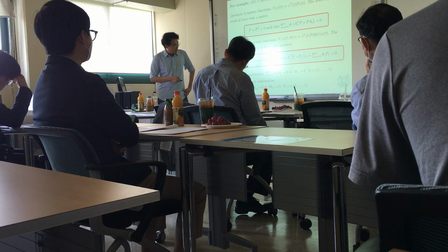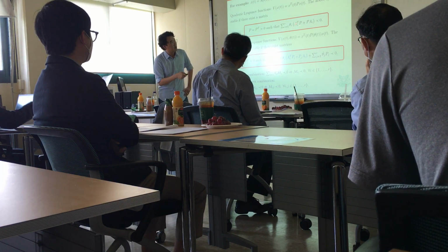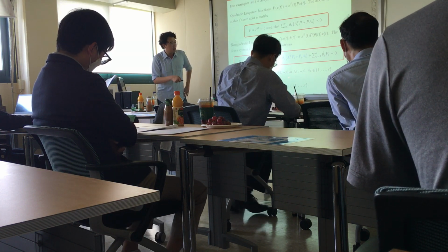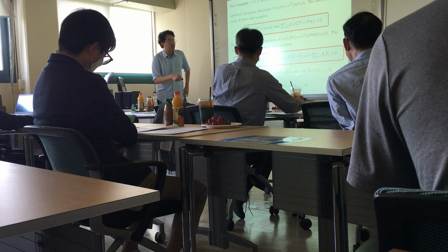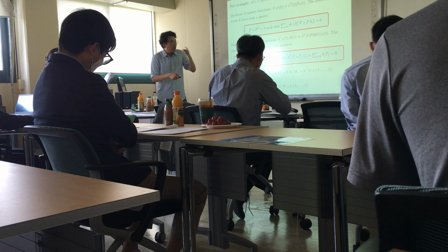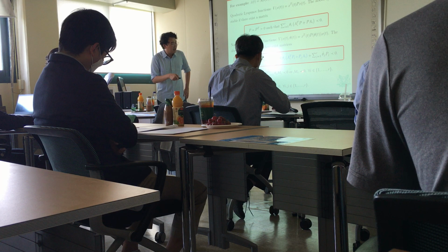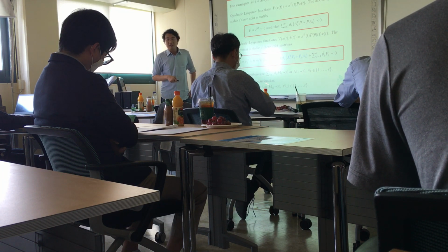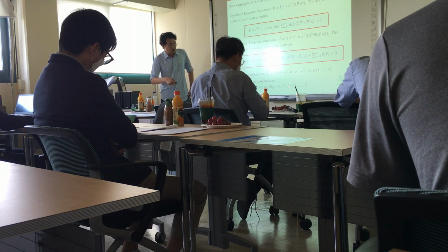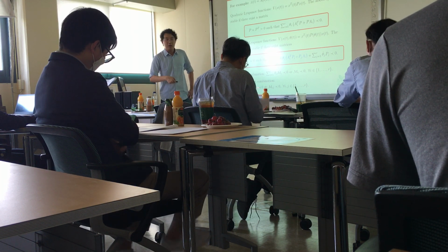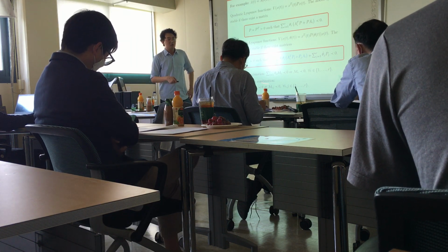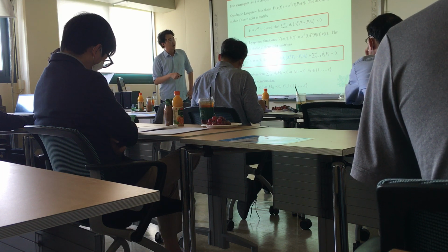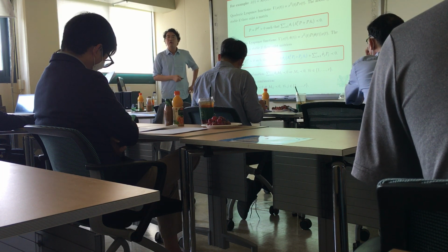Now here is the convex combination, but the convex combination is equivalent to the X matrix being smaller than 0, that is, X matrix is negative definite. In the double convex combination, this equivalence is not true. From the right we can obtain the left, but from the left we cannot obtain the right. That is the reason why we had to choose the non-quadratic Lyapunov function.